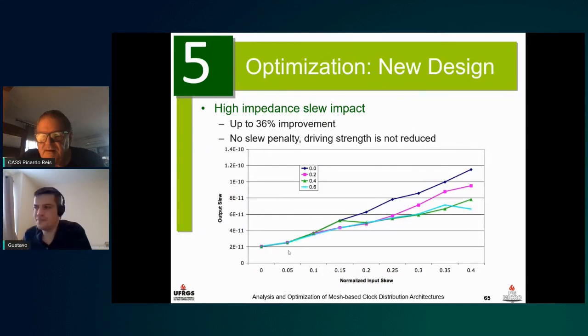Okay, so yeah, the first question, the 20% skew is an indication of both process and environmental variability. From my experience, I don't have any number to quote here, but the main source of clock skew is the environmental variability, so mostly power supply. When the power supply is switching and the circuit is operating with different temperature gradients, you may get large clock skews. The process variability also impacts, but I believe that the highest source of input skew is going to be the environmental variability.